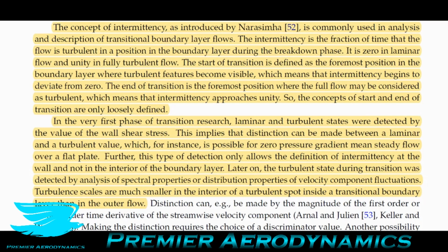It's not completely infallible. So later on, they said, this type of detection only allows the definition of an intermittency at the wall and not in the interior of the boundary layer. In other words, it only looks at the wall and not what's happening in the rest of the boundary layer. And that's important. What's happening at the wall is not the entire picture.